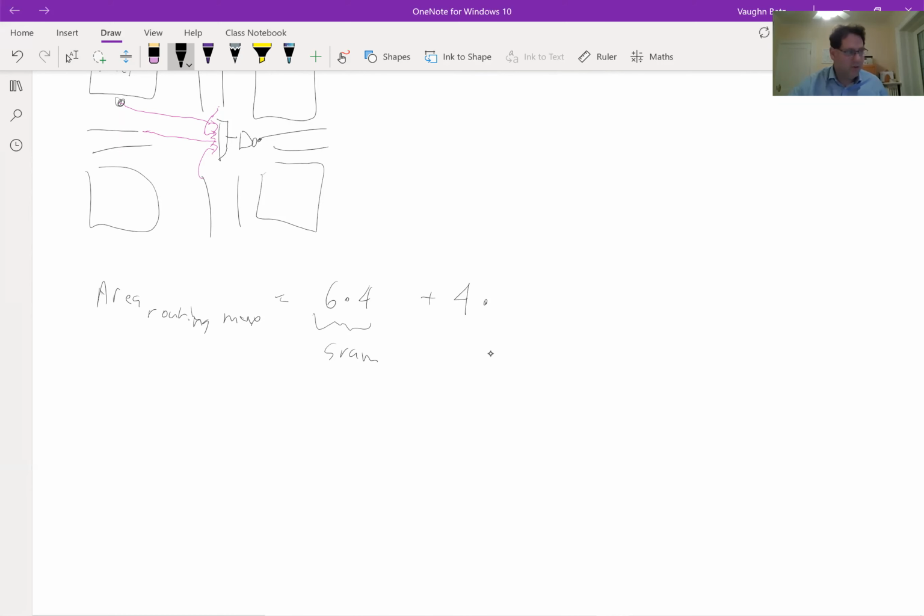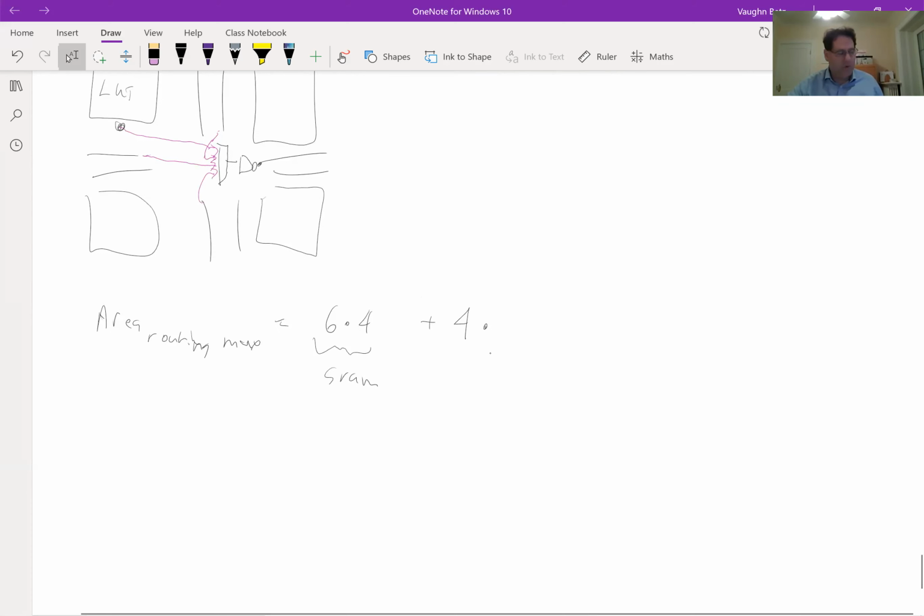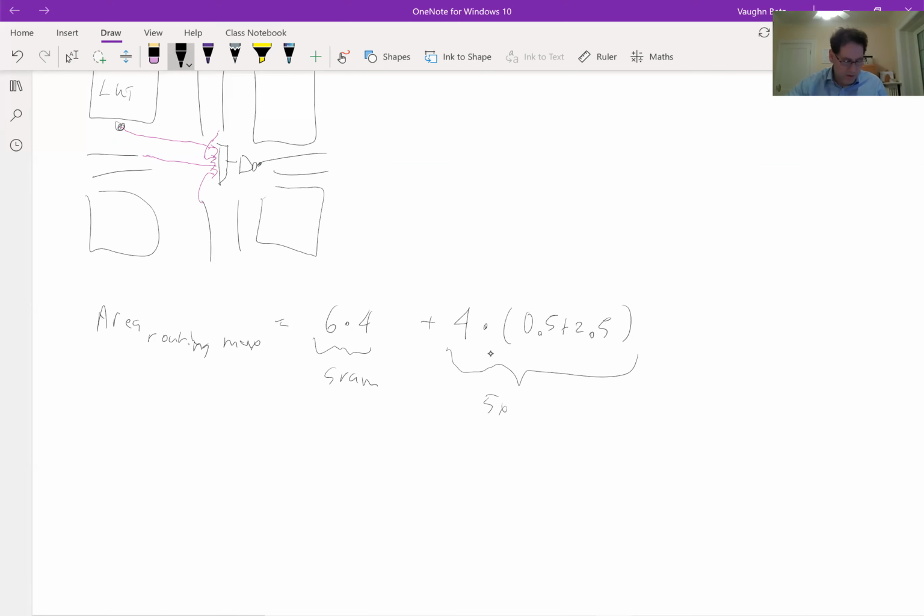We need 4 pass transistors. For a really small mux like this, we're just going to make it out of a 1-level mux. So 4 pass transistors, we're going to make them 5 times the minimum drive strength. So we put that through our area equation. It's 5 plus 2.5. Okay, so these are my 4 pass transistors to make my 4-to-1 mux. And we're making them relatively strong pass transistors, 5 times minimum drive. And at the end, we have an inverter and our level restorer, so 3 transistors for that.